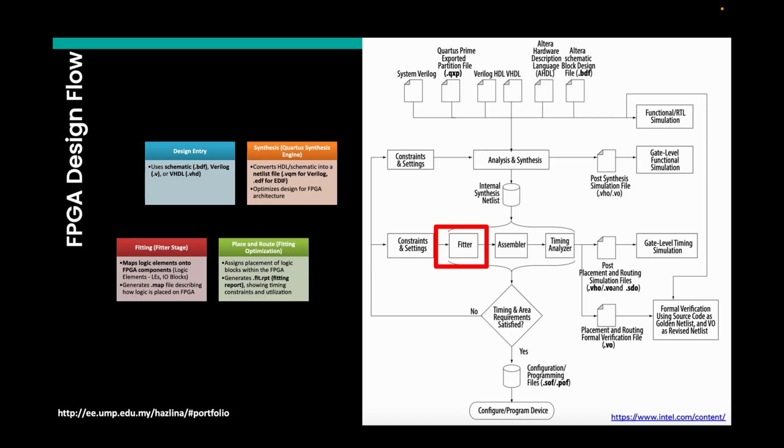Now that the logic is synthesized, we need to map it onto the physical FPGA hardware. This involves assigning FPGA pins for various components. For example, we must carefully allocate I/O pins for the MPU6050 sensor, LoRa transceiver, and LED in the DE10-like Pico satellite project. This ensures correct physical connections and avoids signal conflicts.